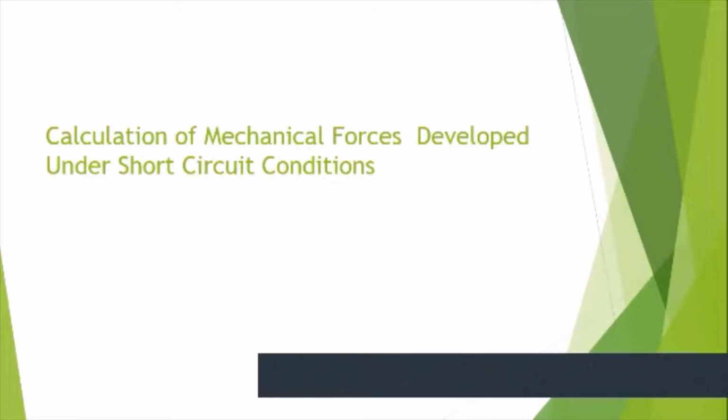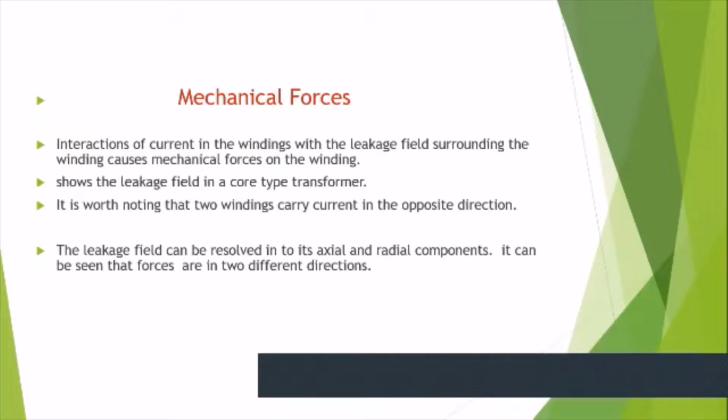Now, calculation of mechanical forces developed under short circuit conditions. So first you should know the mechanical forces. Interaction of current in the winding with the leakage field surrounding the winding causes mechanical forces on the winding.